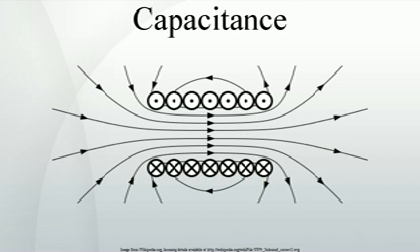It states that, if the gain ratio of two nodes is 1 per K, then an impedance of Z connecting the two nodes can be replaced with a Z/(1−K) impedance between the first node and ground and a KZ/(K−1) impedance between the second node and ground. Since impedance varies inversely with capacitance, the internode capacitance, C, is replaced by a capacitance of (1−K)C from input to ground and a capacitance of (K−1)C/K from output to ground. When the input-to-output gain is very large, the equivalent input-to-ground impedance is very small while the output-to-ground impedance is essentially equal to the original input-to-output impedance.